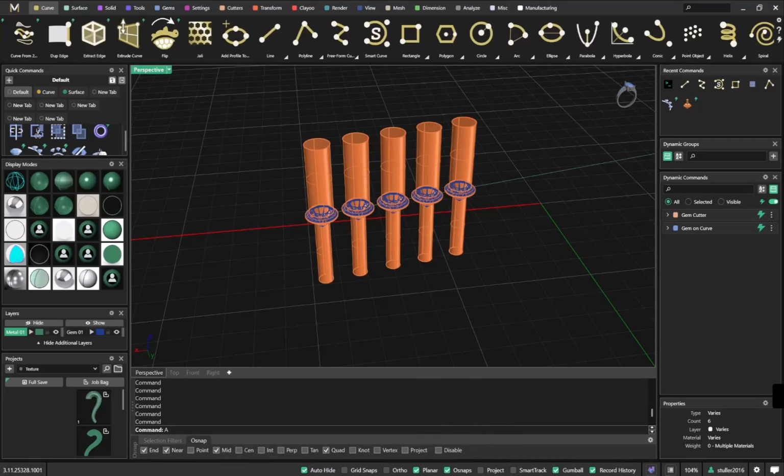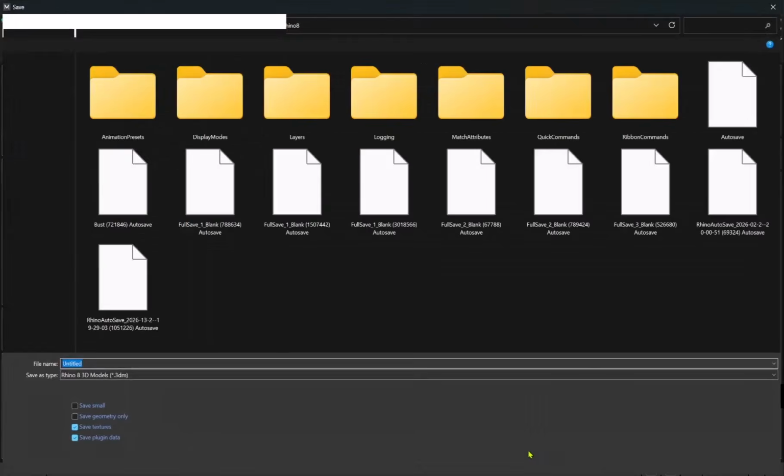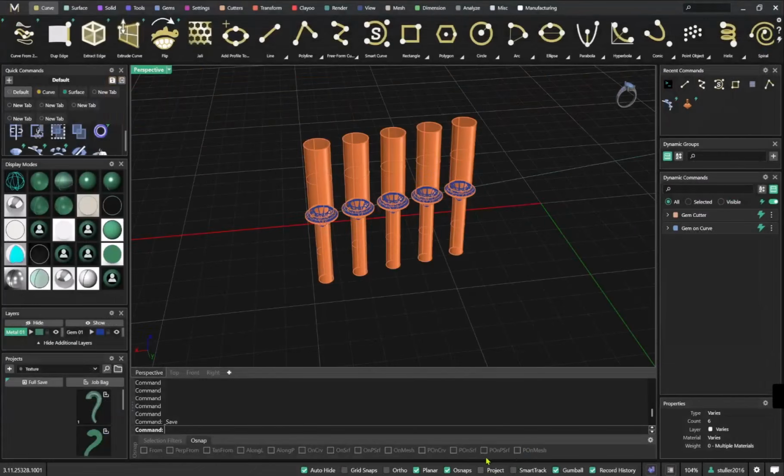They are one-shot snaps, okay, they are not persistent snaps. It means that you need to activate them whenever you want to use them. So press Control and you can access them. And I told you about persist on mesh. It's a very nice feature that we have in MatrixGold, and also persist on polysurface, persist on surface, and these kinds of things.